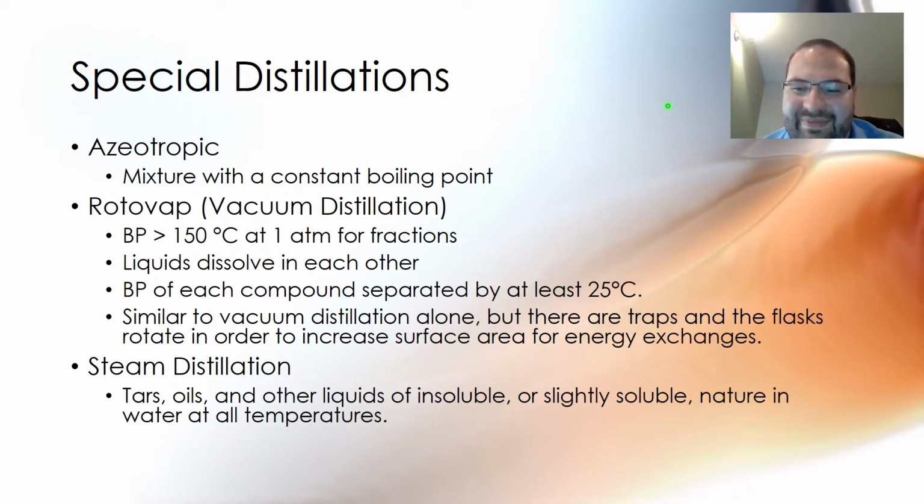Okay, so we're done talking about the equations. That is the general explanation that anybody could provide for how you can look at the boundaries in a fractional column and look at how many plates you have. And you can go up graphically and determine how many you need based on where you are on that mole fraction axis. You could also determine that probably using a system of equations, but I think that might be overly complicated.